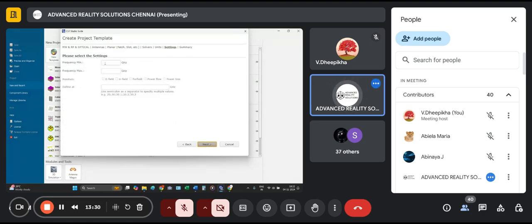Frequency: minimum and maximum frequency. The frequency that we are dealing with is 5 gigahertz. I want to see my antenna's performance over a range of frequencies. There is bandwidth, so I would prefer my antenna to be seen between two different frequencies. For example, my antenna's frequency is 5 gigahertz, so I want to see its performance from 1 to 10 gigahertz, or 4 to 15, or 4 to 10. I mean a minimum value less than my antenna frequency. Let it be 2 gigahertz.